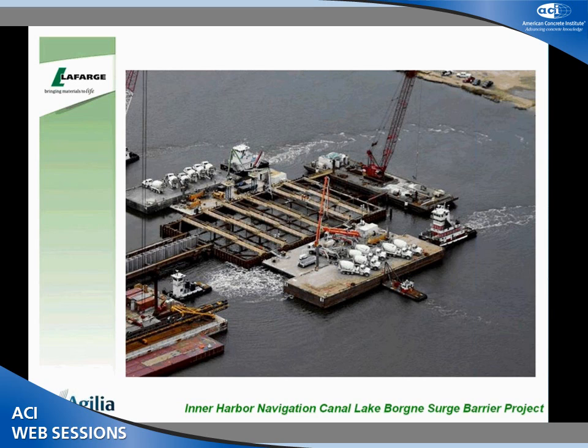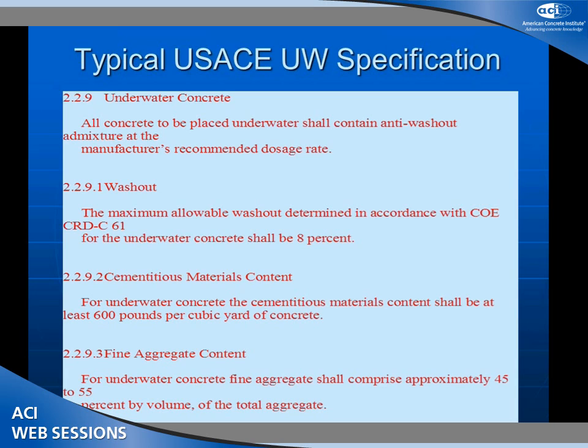It's neutral buoyancy, so there's no real pressure on this. But we've got the thing catwalked and supported at the top to keep it open. They've excavated, they've driven piles. So they've just scraped off about the top 2 foot of muck, so that when they do put the concrete down, it was a limestone bed actually put down 6 or 8 inches, just something to support the plastic concrete as it was being placed.